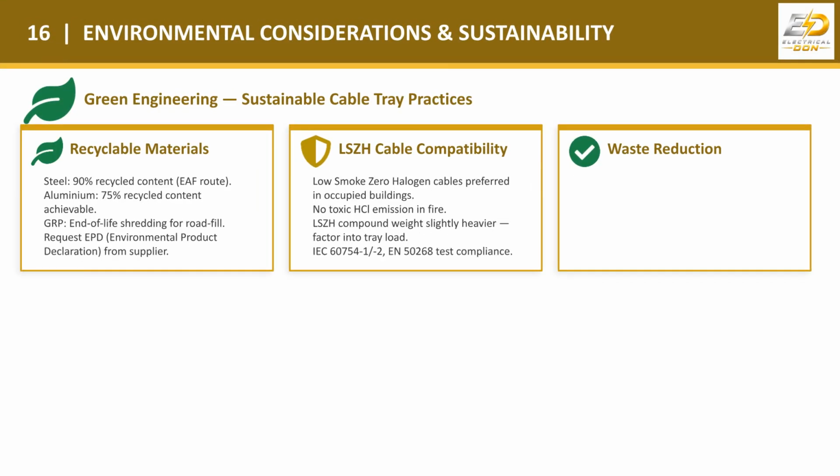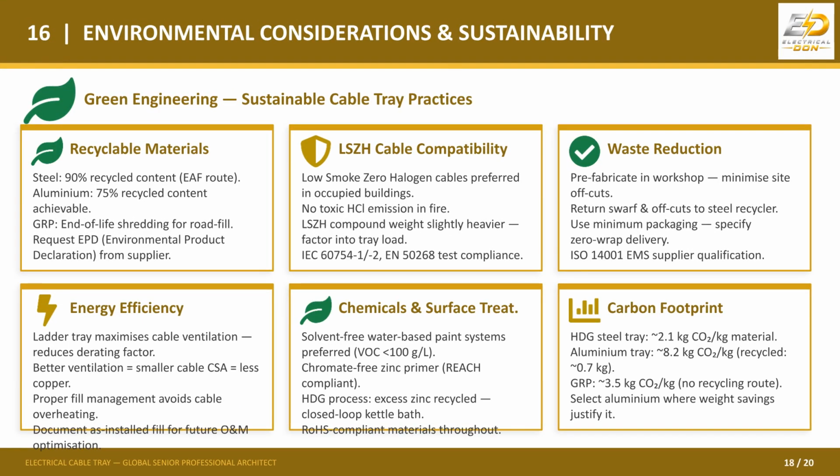Sustainable cable tray practices, or green engineering, focus on recyclable materials, LSZH compatibility, and waste reduction. Recycled content is prioritized, and materials like GRP are managed for end of life. We use solvent-free coatings and minimize waste through prefabrication and zero-wrap delivery. We also look at carbon footprint data to select suitable materials.